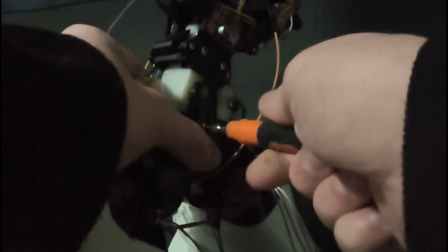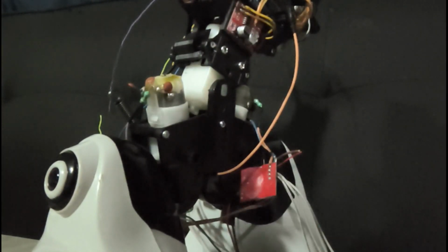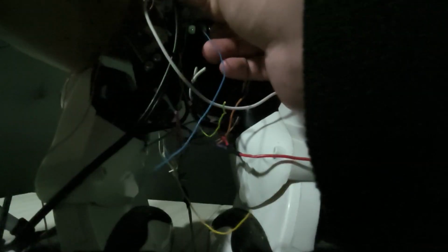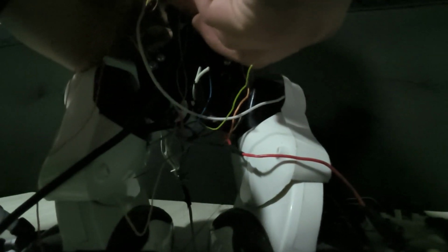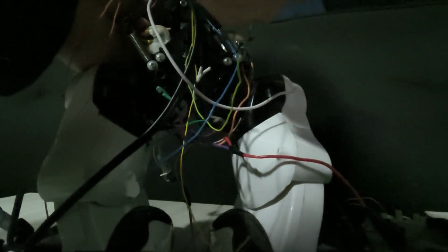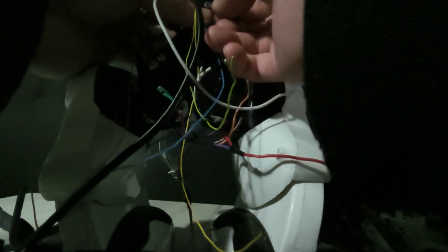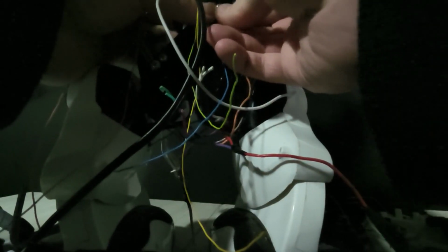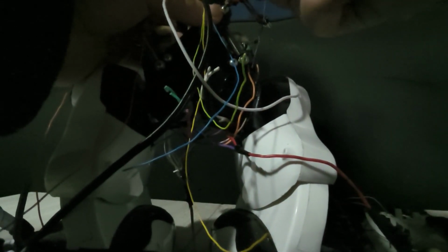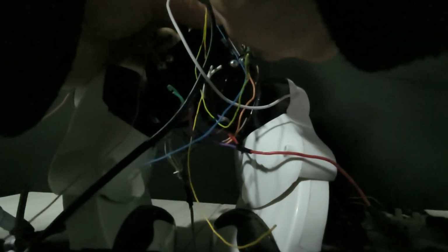Now this is the actual process for putting the robot back together. You screw in the hips, as you can see there. So now we'll go ahead and connect the orange button wires we have for the feet to each foot, and we'll also connect the 3.3 volt line to each of those buttons so the buttons function properly. And we'll also connect the 7.4 volt system to the batteries if you're sure that nothing is shorted, and connect that 7.4 volt positive line to a switch on the back.